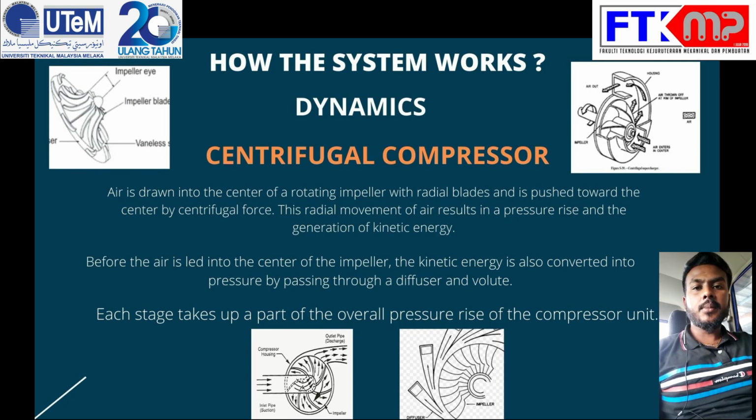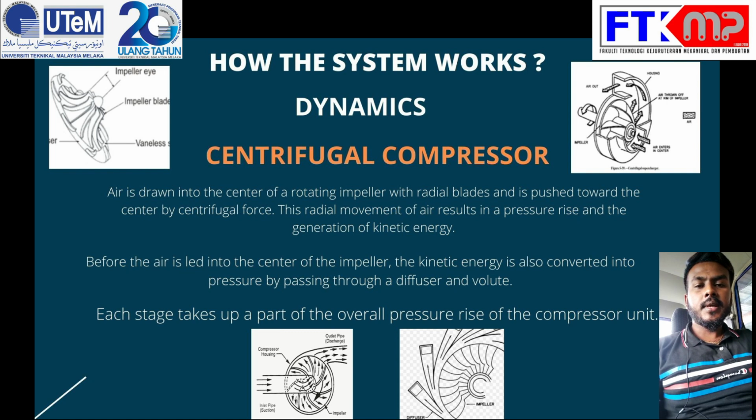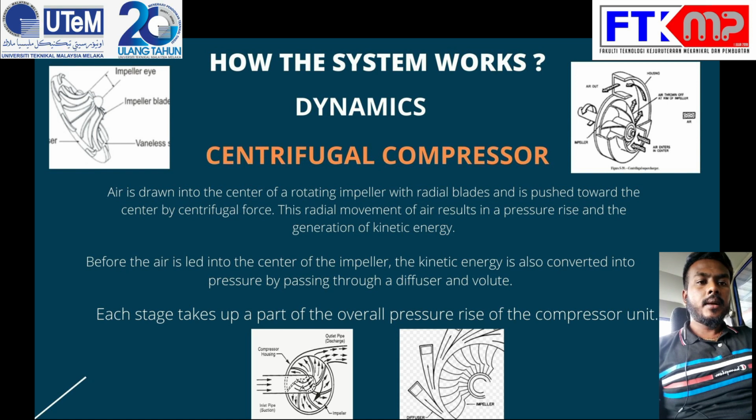Let me continue with another type of compressor, which is the dynamic compressor. Under the dynamic compressor, there is a compressor called the centrifugal compressor. So we see how the system works and the operations. The first operation is that air is drawn into the center of a rotating impeller with radial blades, and it is pushed outward by centrifugal force. The continued radial movement of air results in pressurization and the generation of kinetic energy.